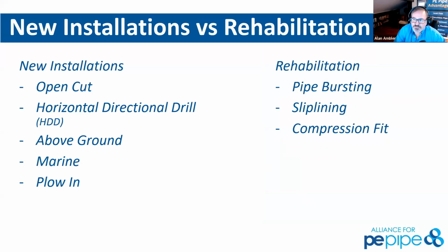There are dewatering pumps, obviously, that you could put in the bottom of that trench. Sometimes it's very common to put in what's called a 57 stone, by its class of what comes through the sieve, to be able to stabilize that bottom. You'd have a lift of all of that to make sure that the workers can access the pipe safely. And then you can also dewater the bottom of that lift in order to remove that.